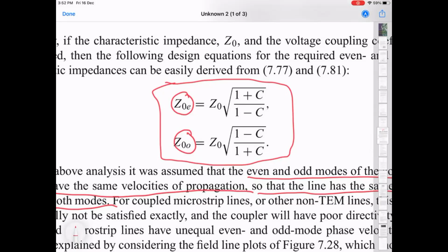These are non-interacting transmission lines, so it's the same as saying I have two independent transmission lines. But the effective dissipation this one sees, if I extend this out here and ask what impedance is seen here, looks like 100 ohms from the point of view of this one, but from this one it looks like 50 ohms. So which is the correct one?